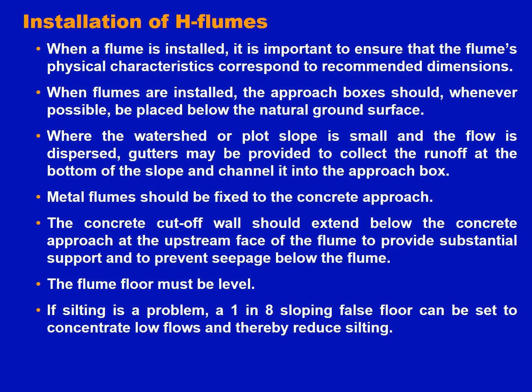If silting is a problem, a 1 in 8 sloping floor can be set to concentrate low flows and thereby reduce the silting. That means, in short, if velocity is low, we have to concentrate the flow, so the discharge will increase and the silting problem will not remain.